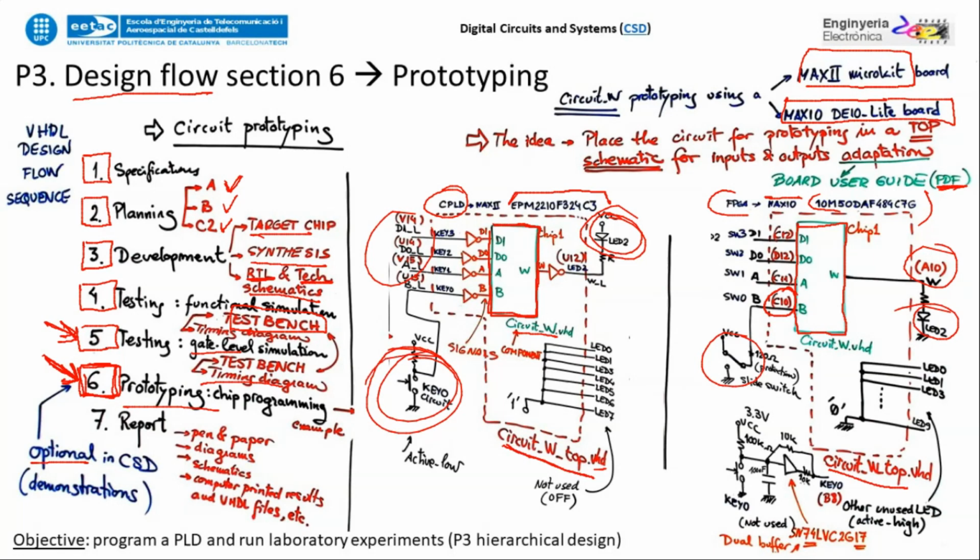So this top architecture is going to be for that adaptation, considering finally that sometimes the schematic is just active low, and you have imagined an active high input. So I mean D1 equal 1 is what you mean, but you see, when you click the button or when you click the switch, what you get is a 0 when clicking. So you need sometimes an inverter, a NOT gate, to do the job of converting from active low key to active high input.